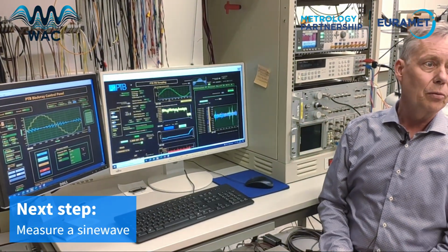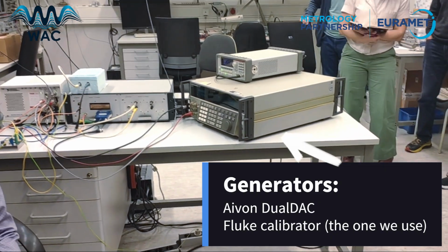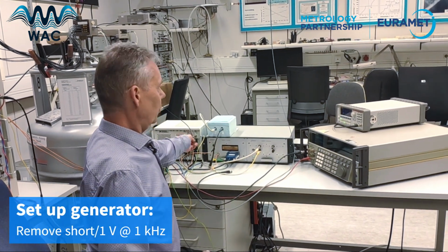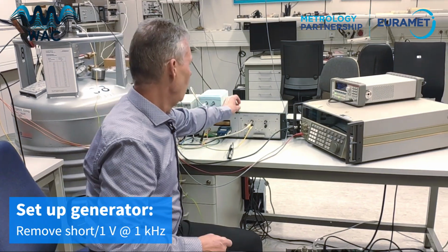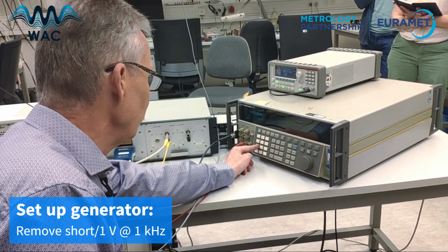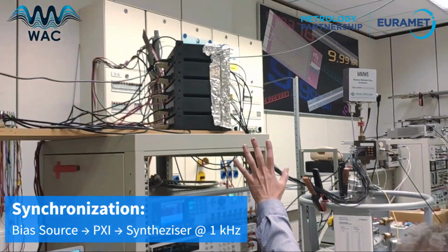The idea is now that we want to measure a sine wave, and we have got two different generators here. I will use the Fluke calibrator on the right side, and I will start with the 1 kilohertz signal. So instead of putting the short for testing the system, I am now connecting the cable of 1 kilohertz. I have to set up the generator here. So I'm going for 1 kilohertz, and the complete system is synchronized starting from the bias source.